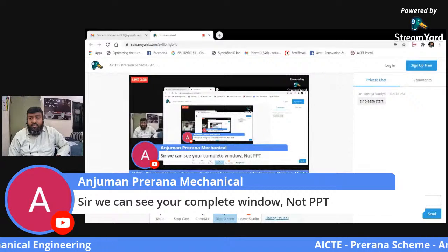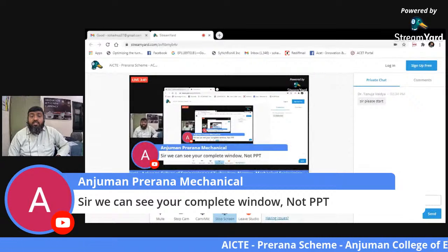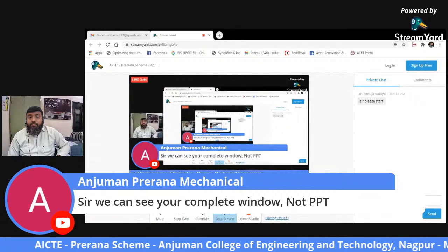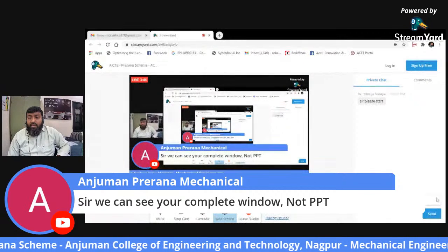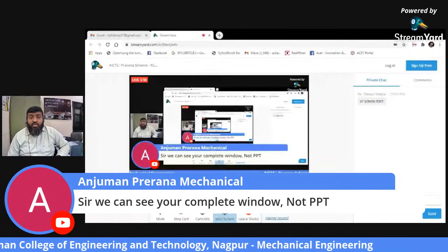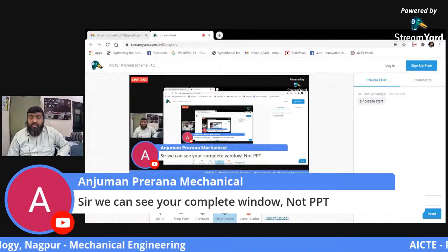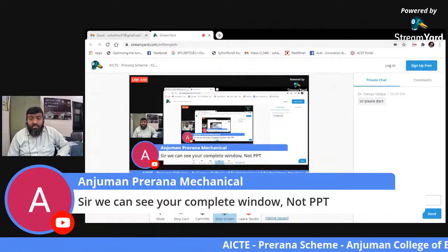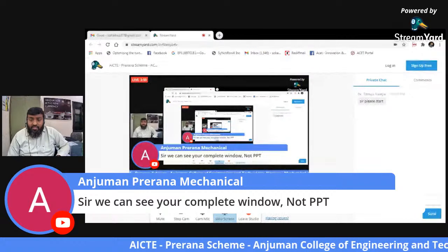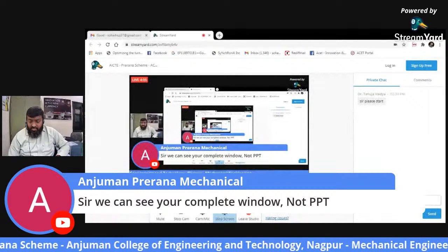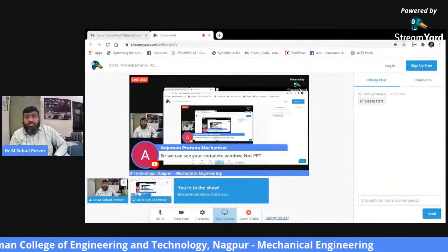Again, the second type of joint is the strength of parallel fillet weld. So these are the parallel fillets. The welds are applied in parallel filleting mode. Again, the same thing, same area, S into L, where L is the length of this weld. So for single parallel, if this is double basically, if it is not there, it is single parallel fillet weld. But these are the basic equations.